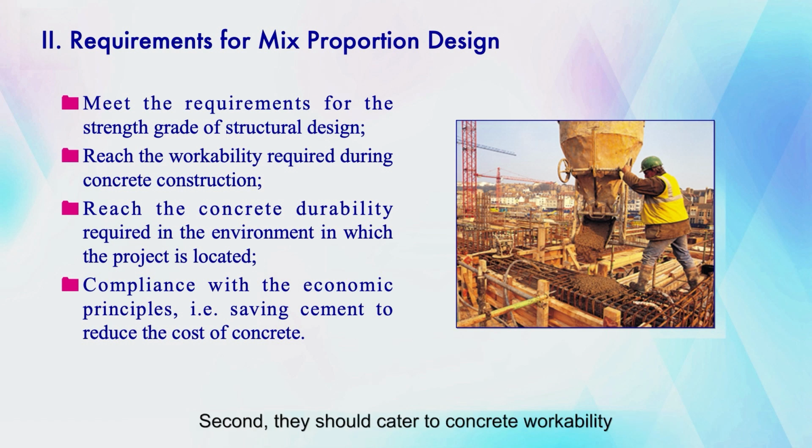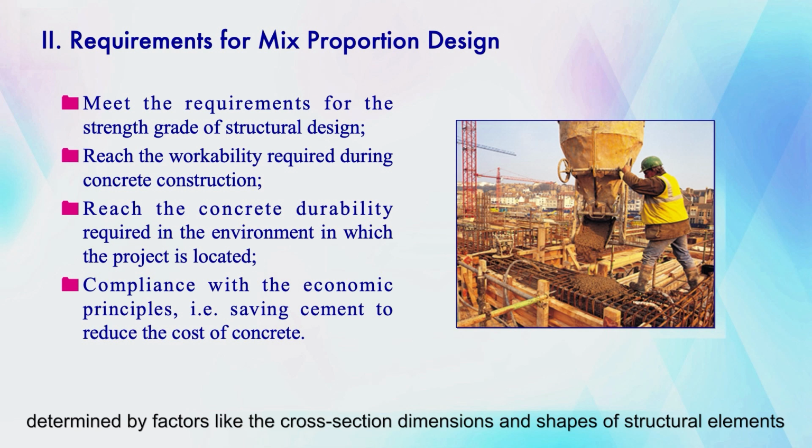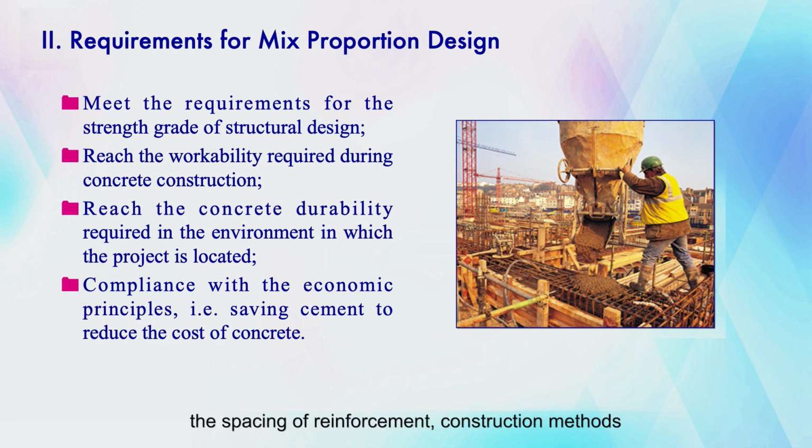Second, they should cater to concrete workability, determined by factors like the cross-section dimensions and shapes of structural elements, the spacing of reinforcement, construction methods, equipment, and other considerations. Third, they should address the concrete's durability, taking into account the environmental conditions the components will be exposed to. This necessitates selecting the appropriate cement type, establishing the maximum water-cement ratio, and determining the minimum cement content.